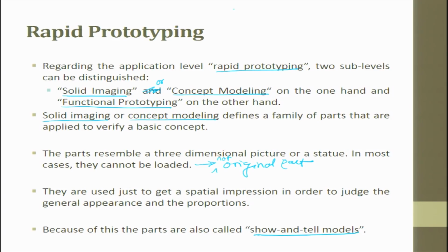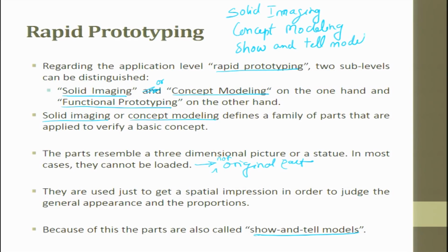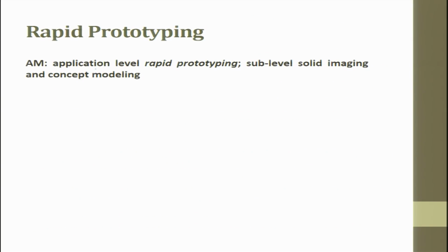So, please understand, solid imaging, concept modeling and show and tell models are all almost the same. It cannot be used for any functional application. So, AM application level, rapid prototyping, sub levels solid imaging and concept modeling.